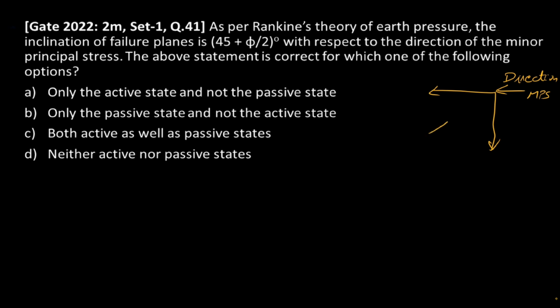And it will be inclined at 45 plus phi by 2, where this one will be vertical stress and this one will be horizontal stress for active earth pressure.